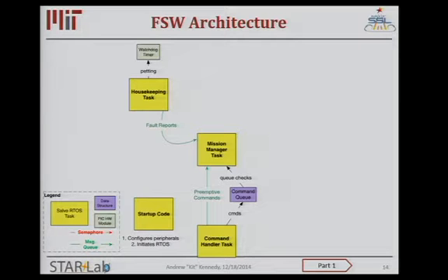Otherwise, as I mentioned before, we have comm blackout periods. We might need to schedule multiple maneuvers in advance for all the orbits during that blackout period. So we have a queue where we're storing a schedule for what modes we want to execute at given times up to a certain planning horizon in the future.